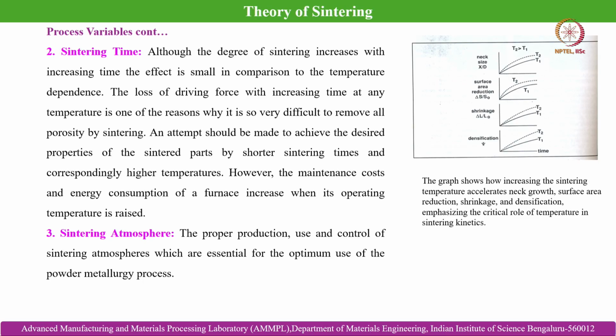The second in line is the sintering time. Although the degree of sintering increases with increasing time, the effect is small in comparison to the temperature dependence. The loss of driving force with increasing time at any temperature is one of the reasons why it is very difficult to remove all porosity by sintering. An attempt should be made to achieve the desired properties of the sintered parts by shortening the sintering times and correspondingly going to higher temperatures.